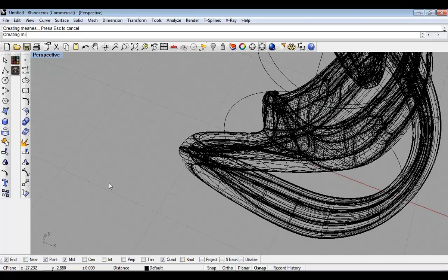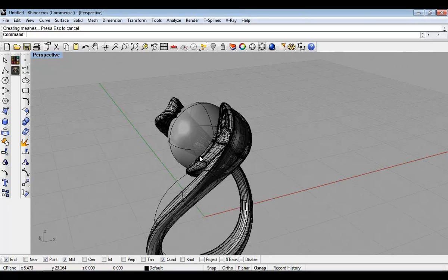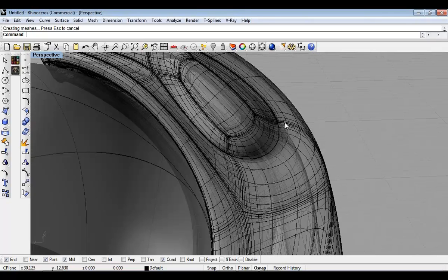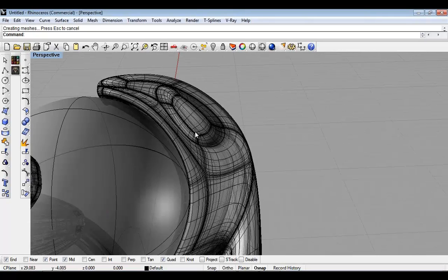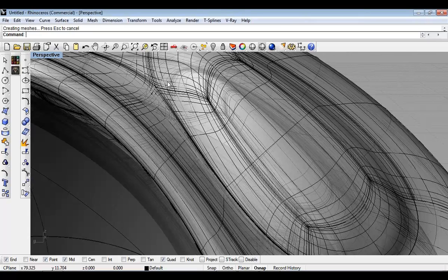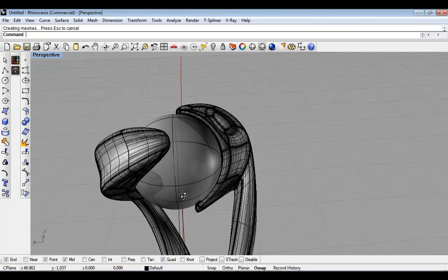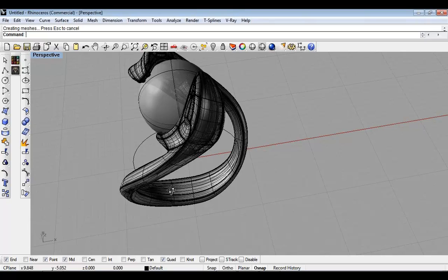Yeah, the reason there are so many points there, Chris, is the star smoothness that you set to 3. In my experience, usually you can leave that at 0, and it actually stays about as smooth. Okay, I've learned something new. Yep, and if you keep that at 0, it really gives you a lot lighter geometry.